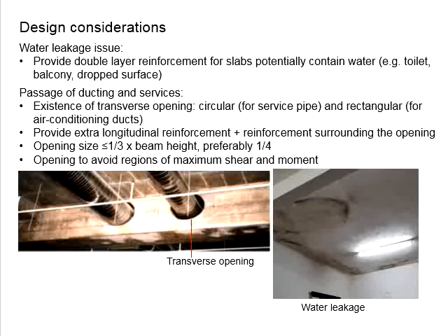For a simply supported beam, the maximum shear will be near the support, and the maximum moment will be at the midspan. As for the continuous beam, this may not necessarily be true. Sometimes at the support, the maximum shear and maximum moment can occur at the same time. Sometimes due to the end condition, the maximum moment may not necessarily be at the midspan of the continuous member. This you need to be careful.